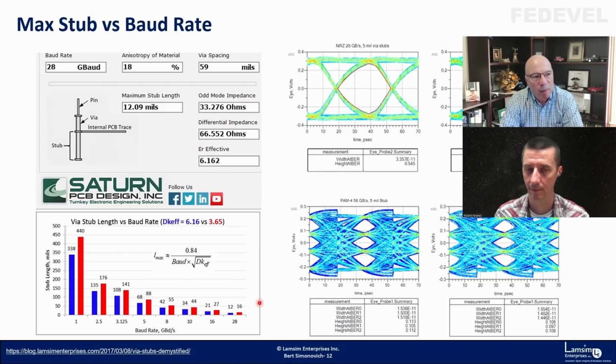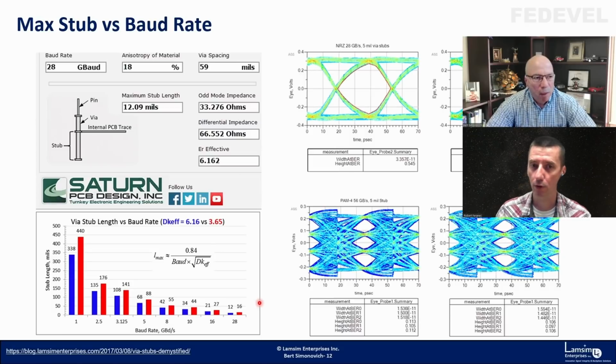Vias in and of themselves can be made fairly transparent in a design. So if you use proper vias, then for very high speed signals, it's actually better to go down to the bottom layer than continue. You don't always have that luxury because you have several layers, so every signal can't go to the bottom. But in principle, yes, there's some kind of loss going through, and you need proper stitching vias, of course, to go through all of this.